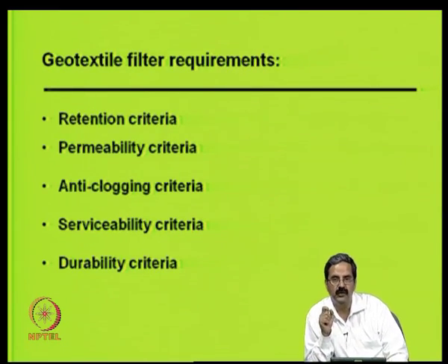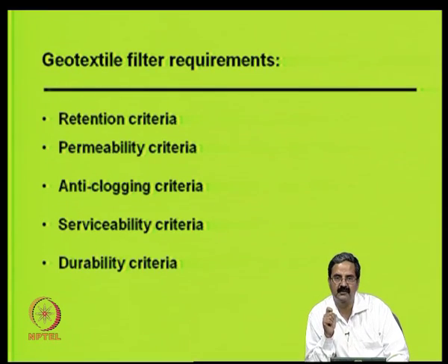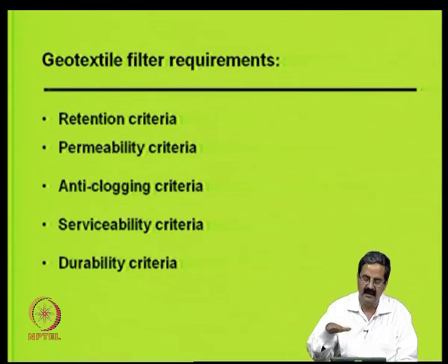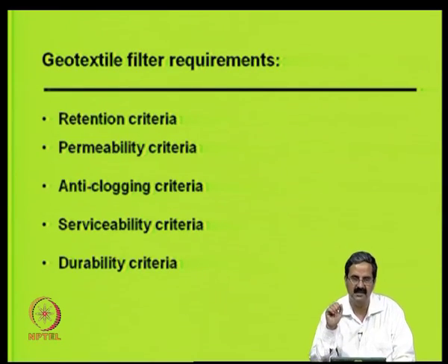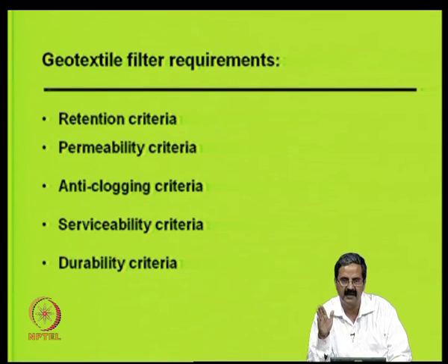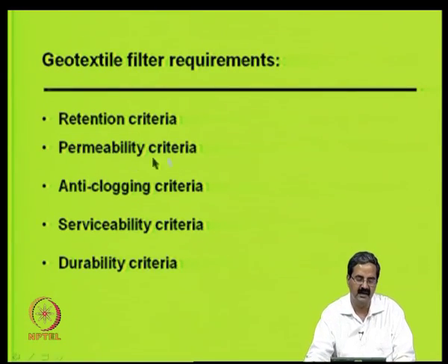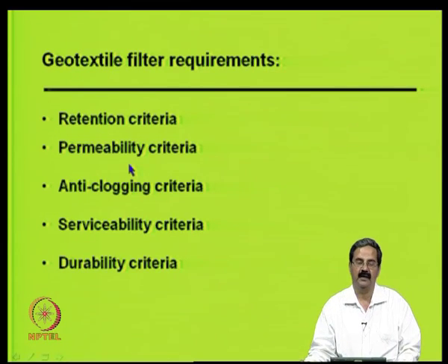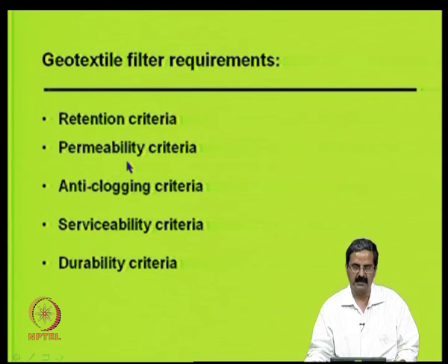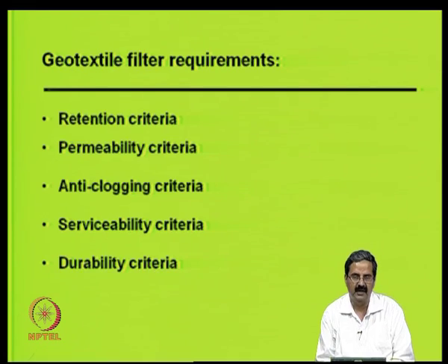So now we know that geotextile performs better for the simple reason that it cleanly removes the water, and thickness is less. We saw the differences between a geotextile filter and a regular filter like an aggregate filter. The difference is good, and if you are putting the geotextile, you should also design it properly. One is retention criteria and permeability criteria and anti-clogging. So people have thought that the criteria of just soil retention and permeability may not be sufficient. We should have some more information.